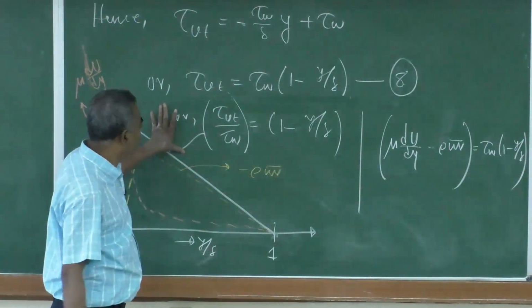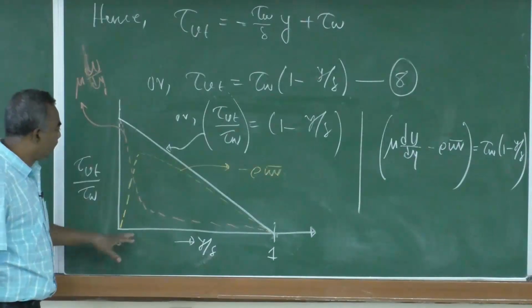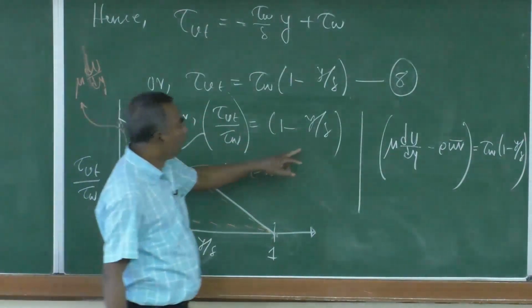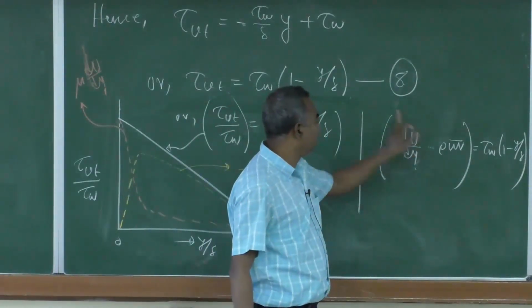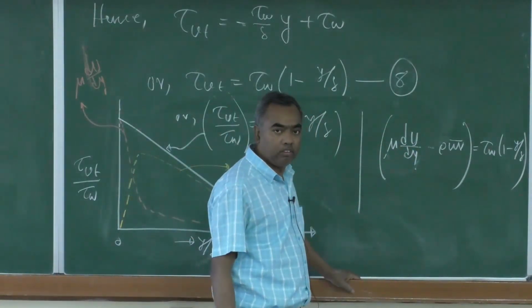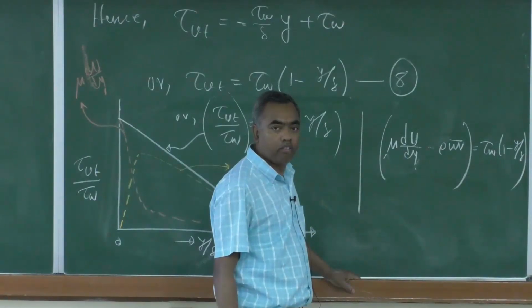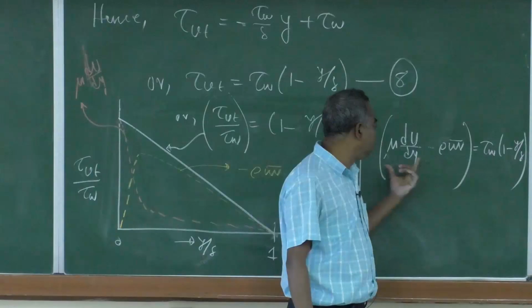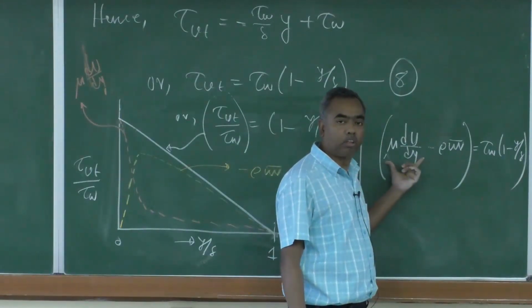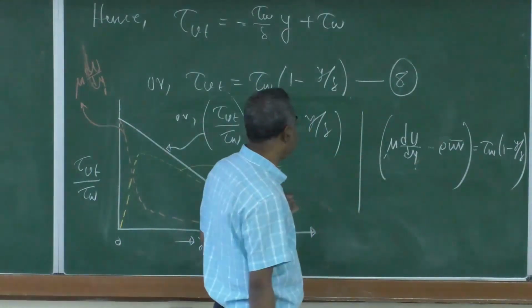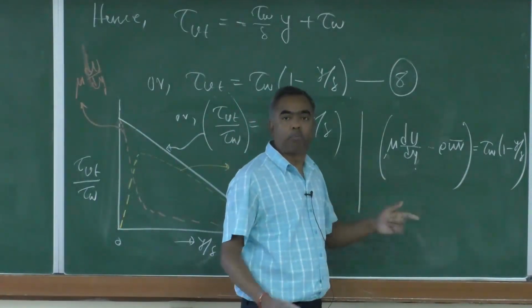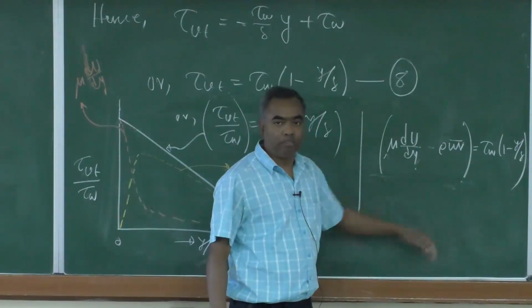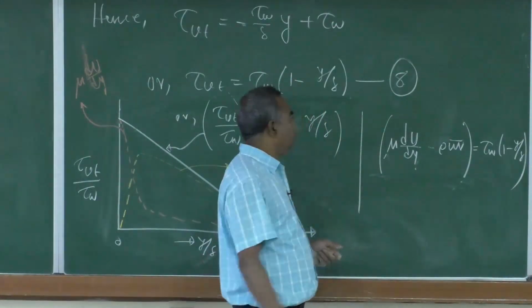Before I proceed, let me just give you another brief overview. In the case of free shear flows, this particular part, the viscous part, was negligible, okay? Whereas only this quantity is important in free shear flows, this quantity is negligible for free shear flows, okay? Because free shear flow is not bounded by walls. So, that is one very important observation comparing these two flows.